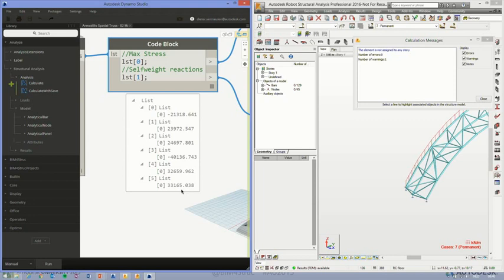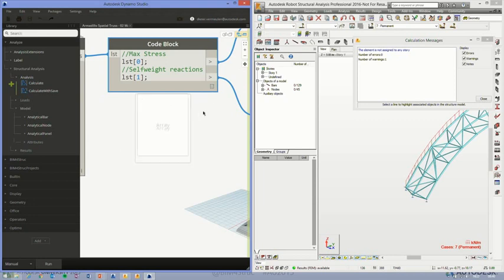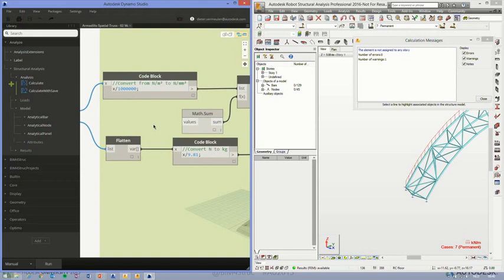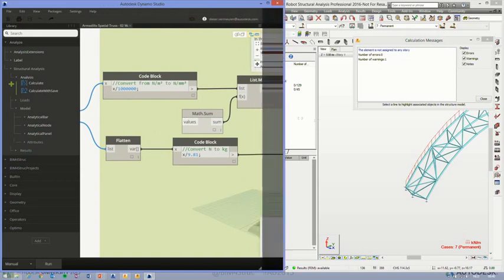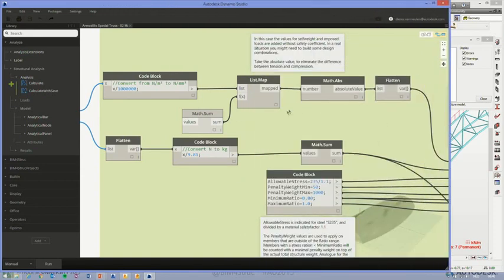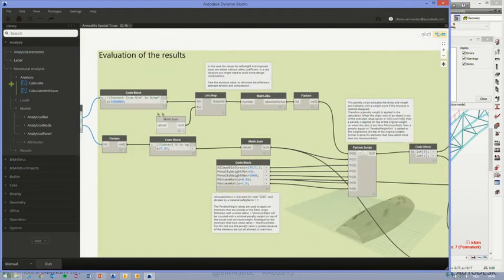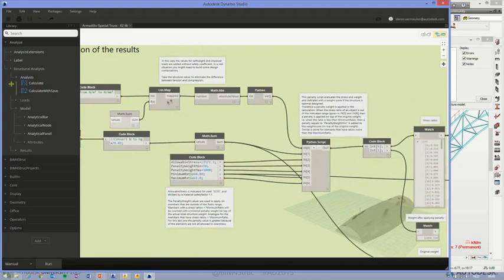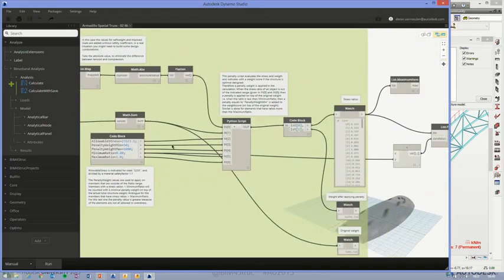Okay? Then if that one works, and if you change the parameters up front in the system and you see it working in Dynamo and in Robot, then you can go to the next phase, which is the manual parameterizing phase. I tend to call it something like parametric run. Now, what happens in here is that I made a custom node called the Armadillo Spatial Truss Analysis, which contains the whole project that I just showed you a few seconds ago.